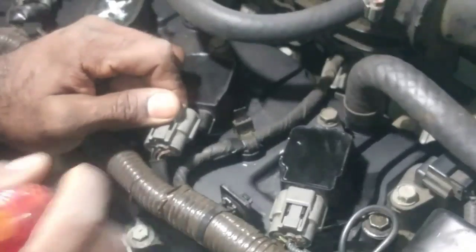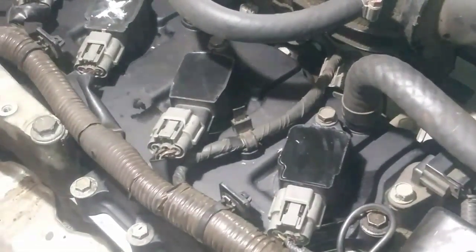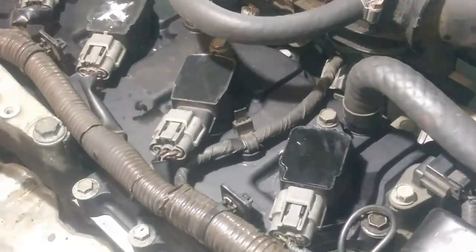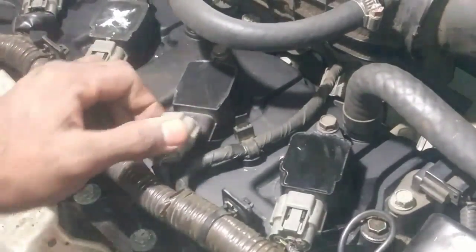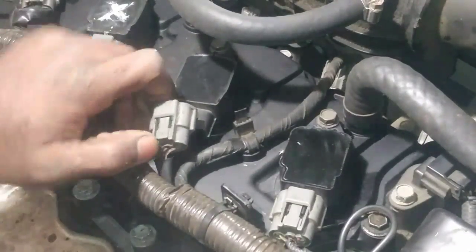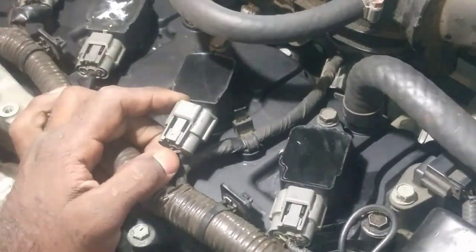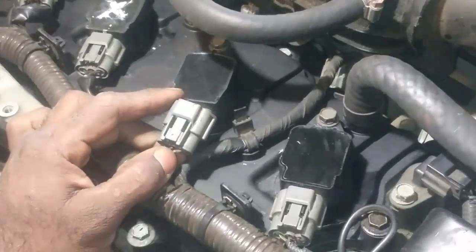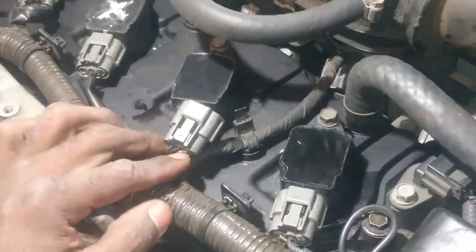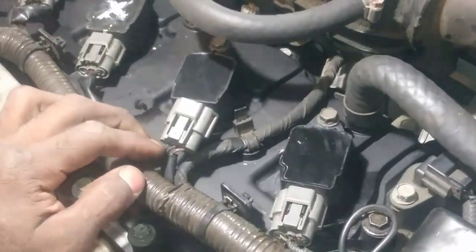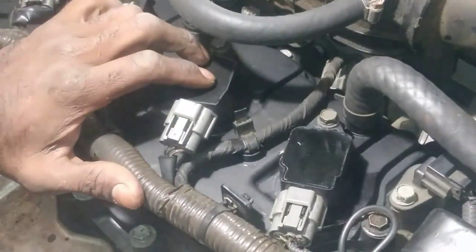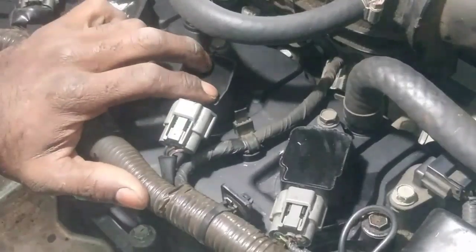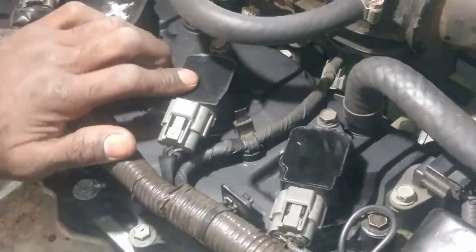But what we're going to do to look at the signal, we're going to connect our oscilloscope to the 12-volt side, and we should be able to see the event occur. And we're going to connect to the signal side so we can look at it. It should be a square wave that goes inside this coil here, not an AC wave signal.